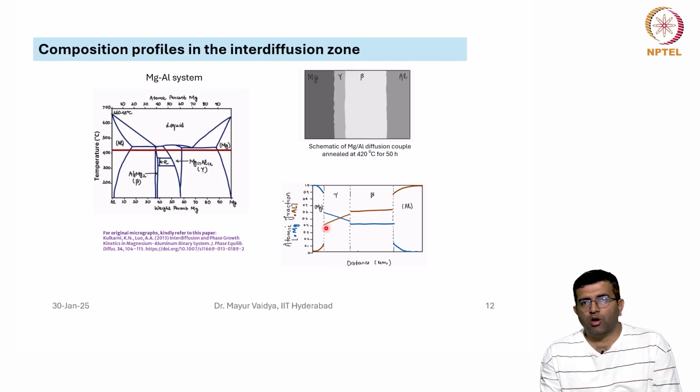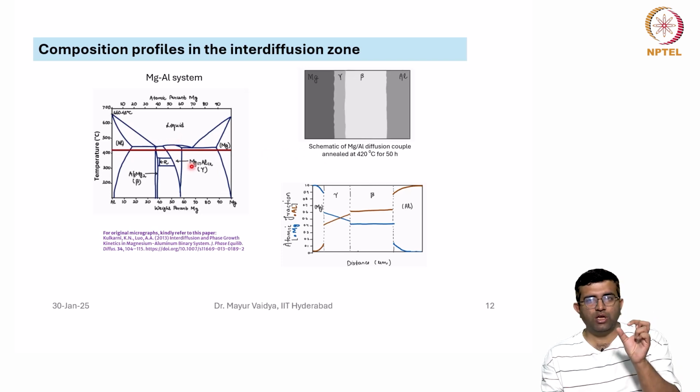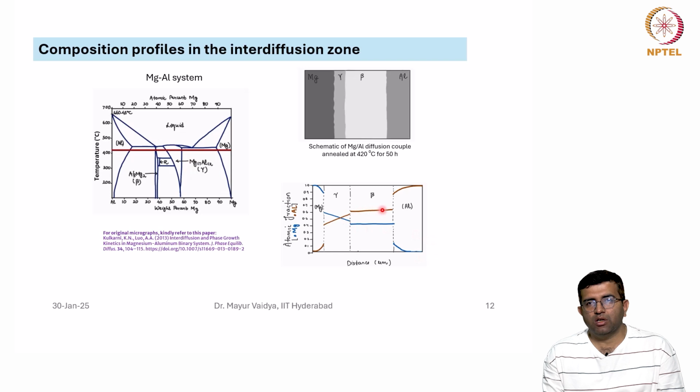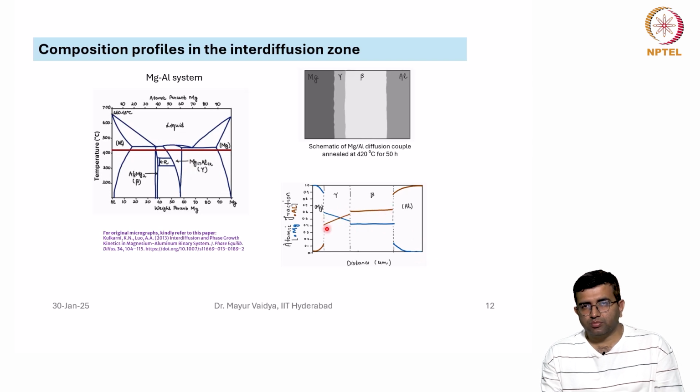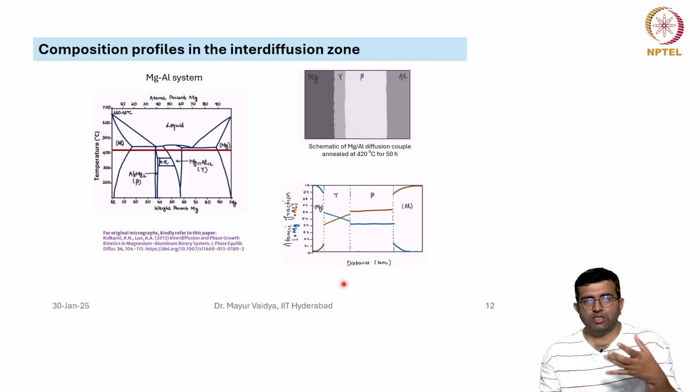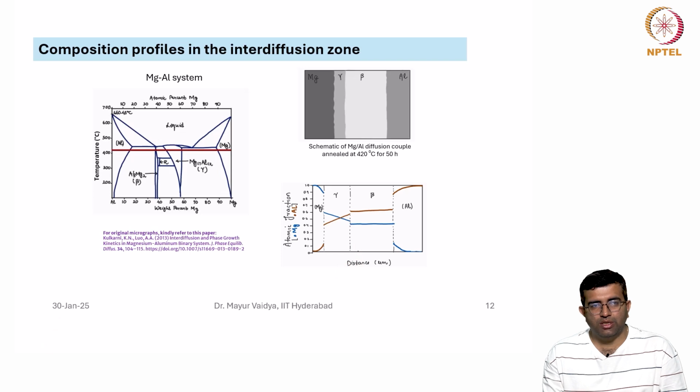Therefore, in the composition profile you see that we have some gradient in the gamma phase, but beta is horizontal. So, depending upon the nature of the phase, whether it is a wide phase or a narrow phase, you can expect to see either a gradient or a horizontal line. We saw several such examples in the video, so I definitely suggest you practice on this as well.